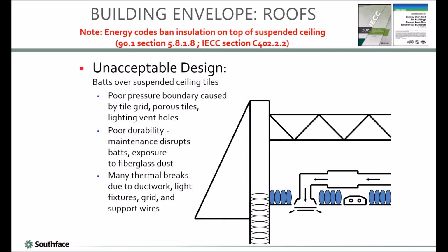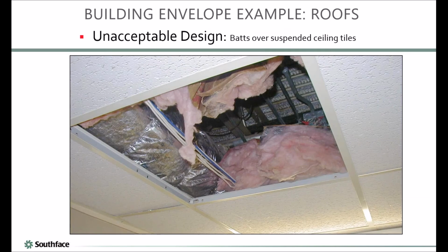So this is not an acceptable way to comply with energy code in terms of meeting the R value requirements for the ceiling. Mike, I think you and I have both seen where you pop a ceiling tile and it looks kind of like that. It's just a mess, and it doesn't get better with age.